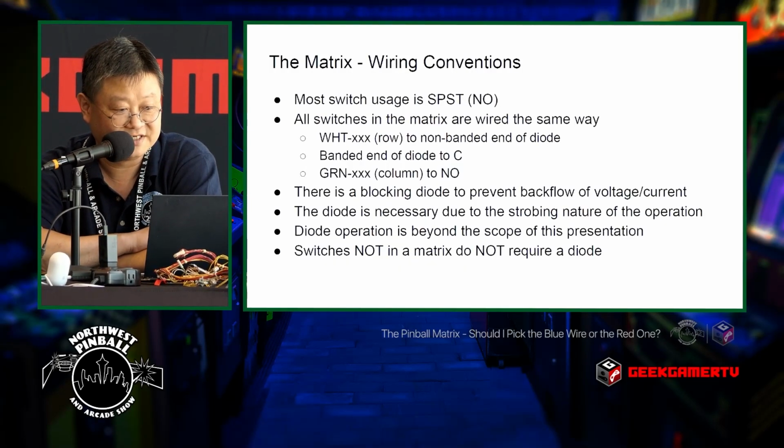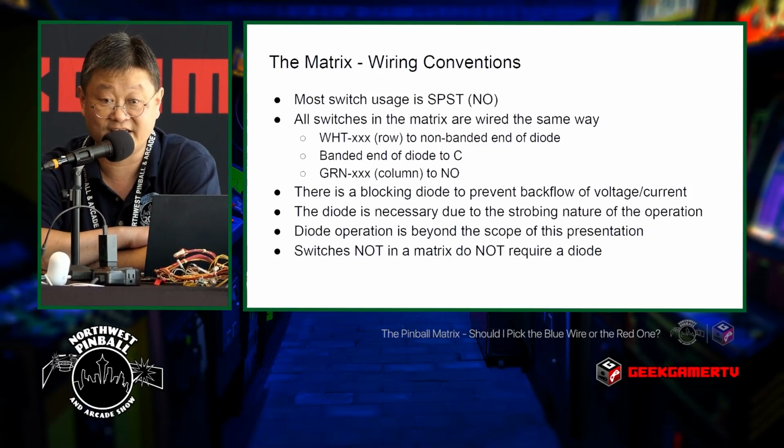Wiring conventions. Okay, so most switch usage is SPST-NO. Any switch that's in a matrix, not a direct switch, is wired the same way. The white wire goes to the non-banded end of the diode, the banded end of the diode goes to the common terminal, and the green wire comes out from the normally open terminal.